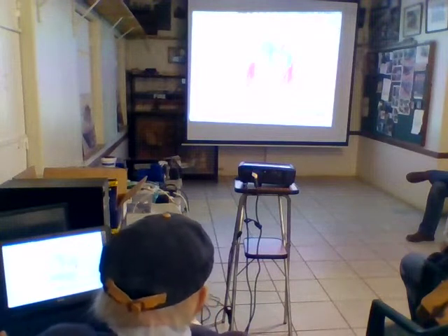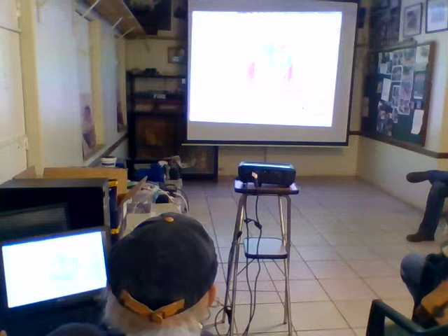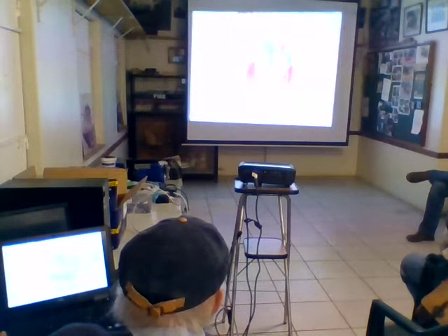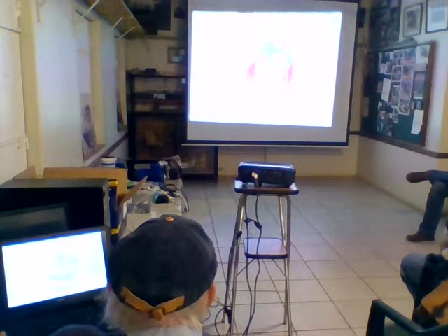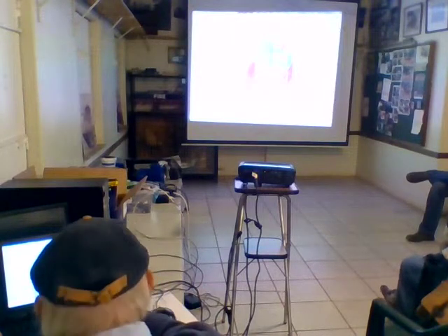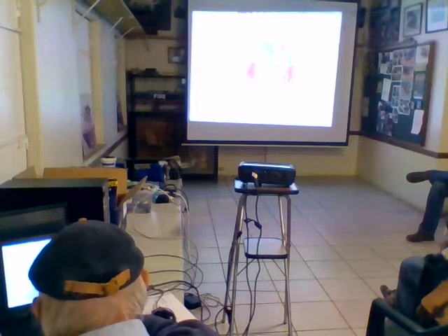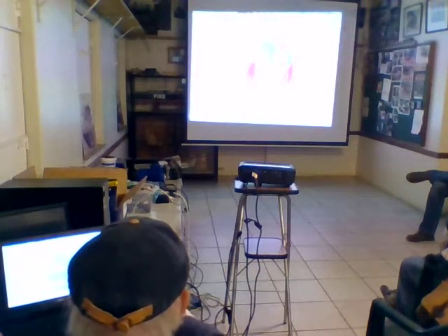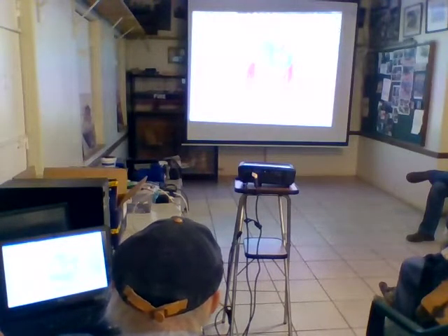But I can change that with software, and I can increase the actual deformations by a scale factor. So this model is in millimeter. So if I put a factor of 1000 in here, then all the movements will increase by a factor of 1000.